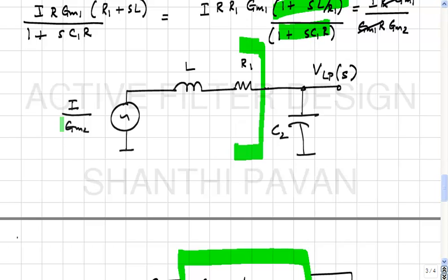So you could have replaced the voltage source, the inductor, the capacitor and the resistor in series with a gyrator terminated by voltage source becomes current source, series becomes parallel, inductor becomes capacitor, resistor becomes conductance, which is the same as a resistor, right? So we could have realized this voltage source in series with an L and an R by a gyrator